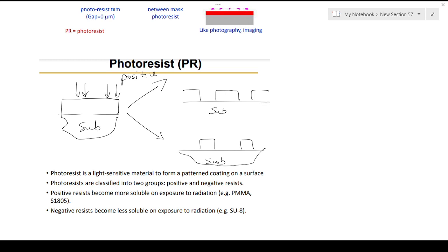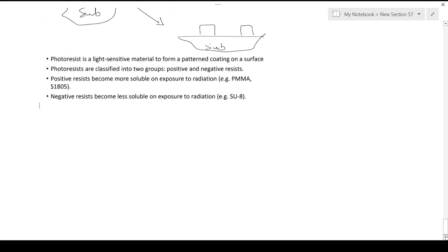One of the limitations of this process is that the light is passing through a narrow object, so the patterns or mask features should be on the order of the wavelength of the light. Then only can you observe the corresponding diffraction pattern, which leads to the proper masking process.